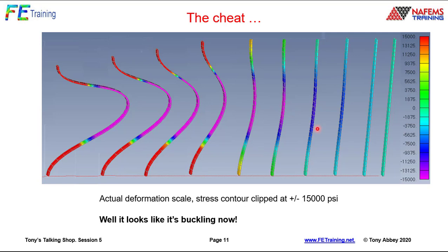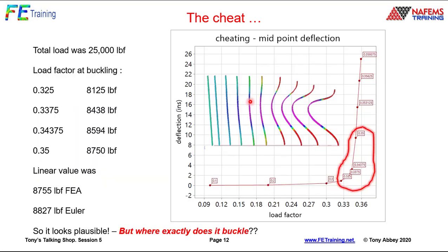The first four here, what we call purely geometric nonlinear. That's basically got the buckling going. It's updating the stiffness matrix in the presence of the configuration change and putting some stress stiffening terms and so on in there. Beyond that, again, it should be yielding. So it's an interesting picture, but it's really a silly answer beyond wherever we got the purple, or just over the purple, just over 16,000 psi in there.